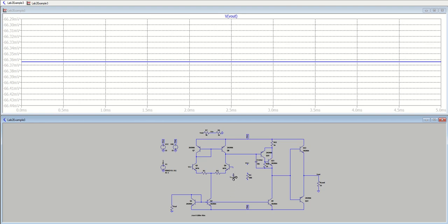So what we did in the beginning is we set both inputs to ground and we measured the output, which theoretically should be 0. Well, if we send the same signal into both inputs of the op-amp, you're taking the difference of the two, so they should cancel out and you should also get 0. So let's go ahead and try to do that.